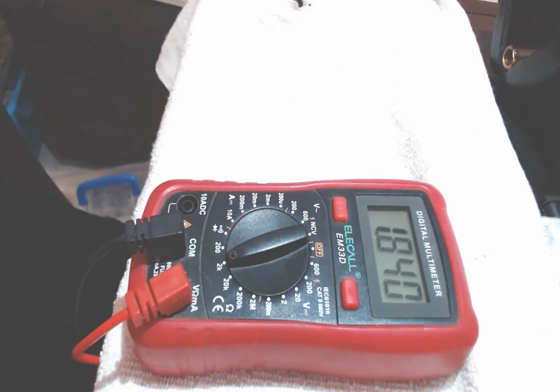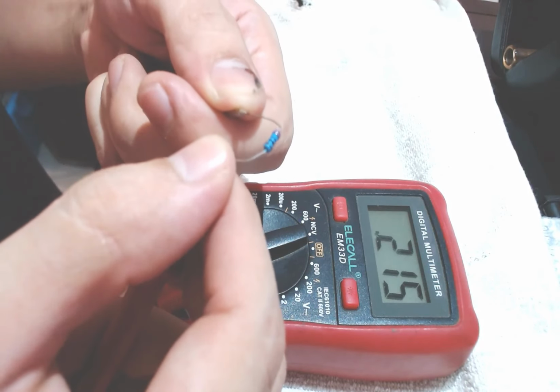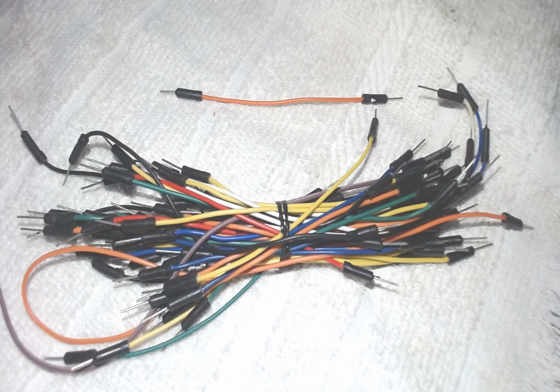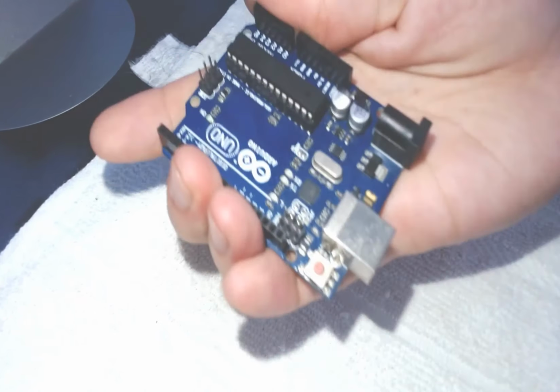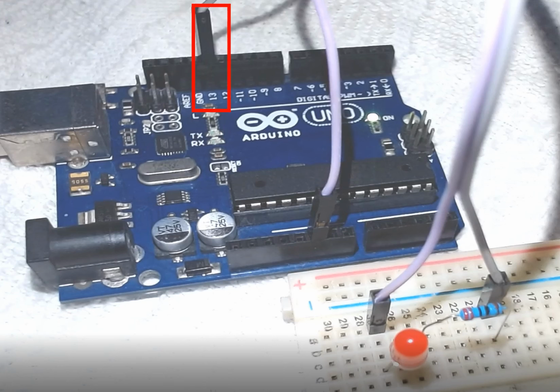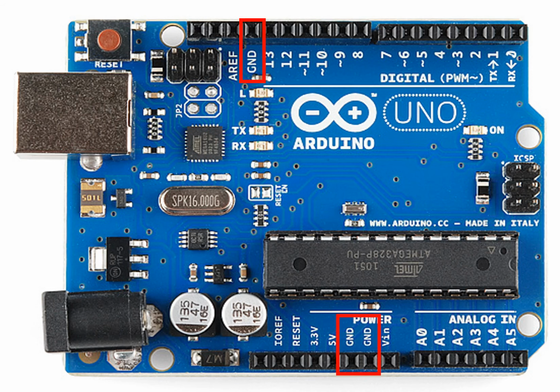In this case, and for the type of LED I will be using for the Arduino board, I will use a 220 ohms resistor. I will also use cables with male pins on both ends and a circuit board to make our connections. Remember that it's recommended to disconnect the power source of the Arduino while making connections. Let's connect a wire to pin 13, followed by the resistor that will be connected to the anode of the LED. At the cathode, the wire will have a shared ground on the circuit board. Ground is found as GND in the Arduino board.